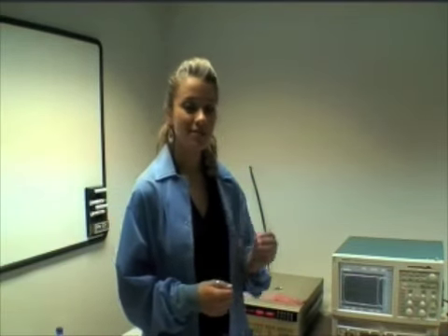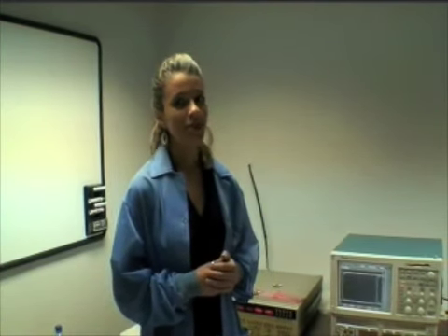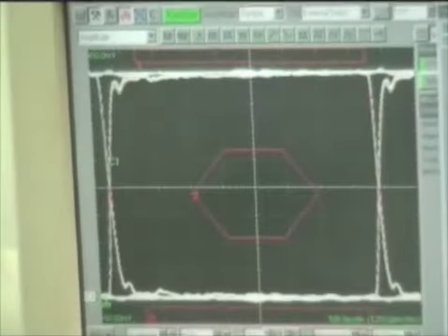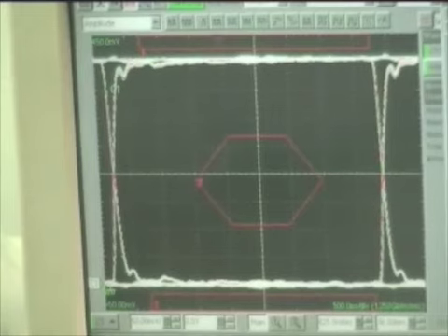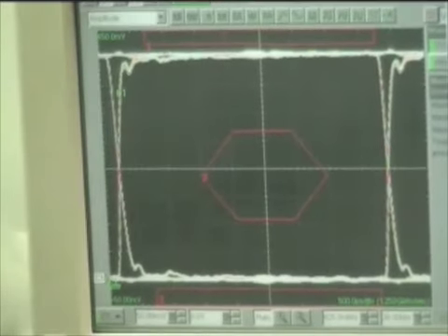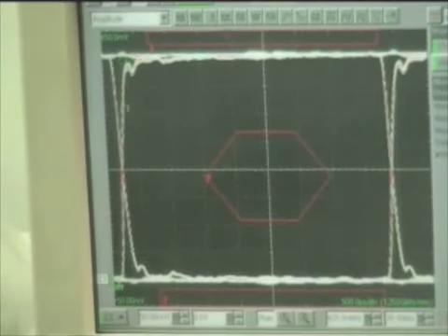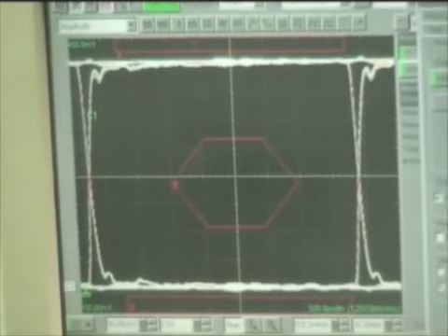The last part we're going to be evaluating today is the ESD9L5.0 device. This device was created specifically for high-speed data signals such as the USB 2 at 480 megahertz. It has a low capacitance of 0.5 picofarads. The ultra-low capacitance of the ESD9L device offers a good design option for semiconductor devices for USB 2 high-speed applications.